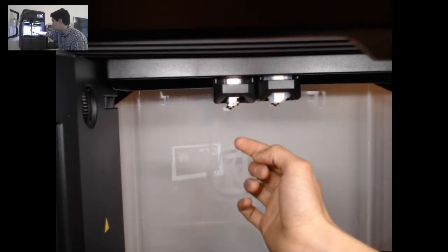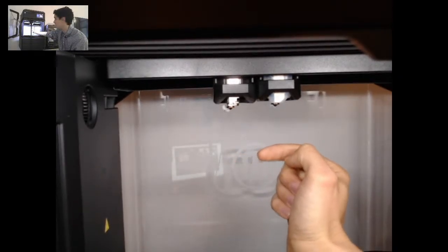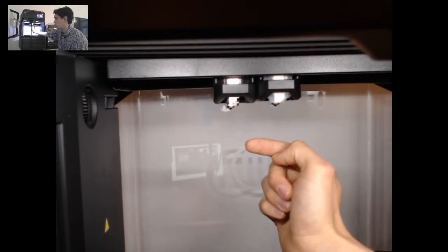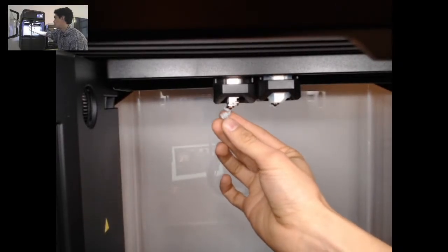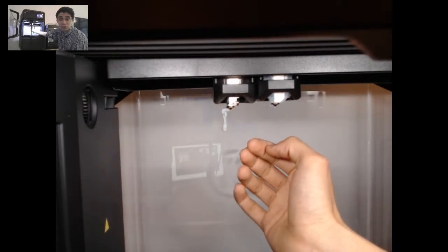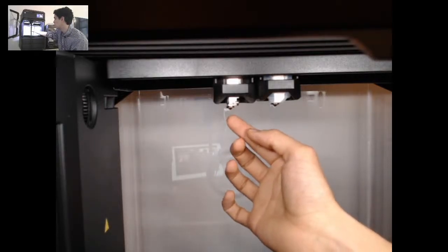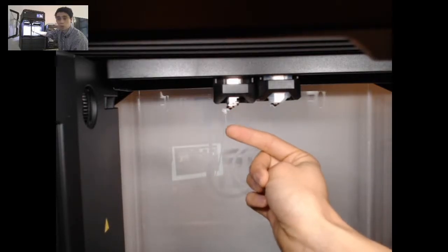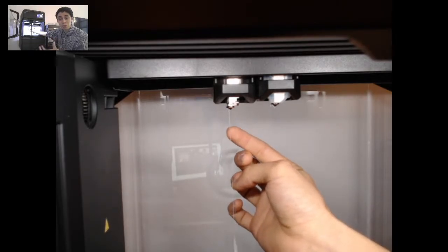If you have to use one extruder and toggle between different materials, what I would recommend is doing a few runs of the purging process just to make sure that the filament is actually coming out clean and pristine. In this case, it's a little bit easier because I have white polycarbonate coming out, so I can wait until the filament coming out of my extruder is completely white to know that my extruder is now clean.